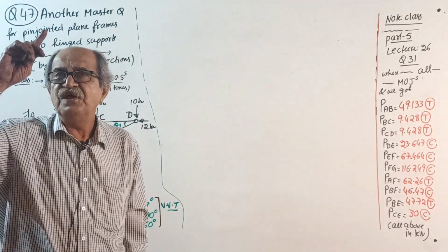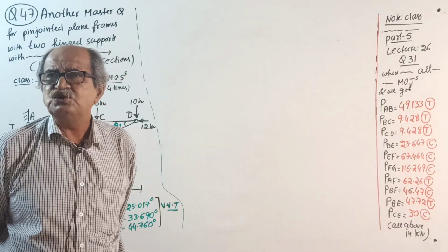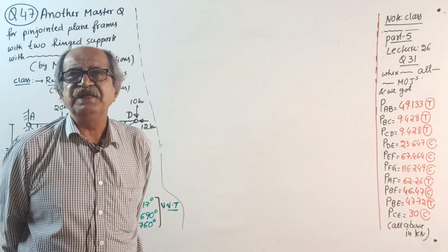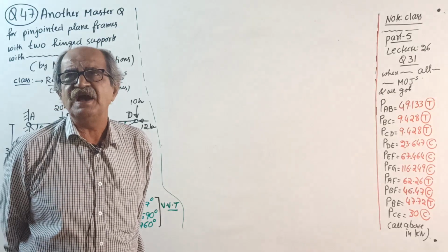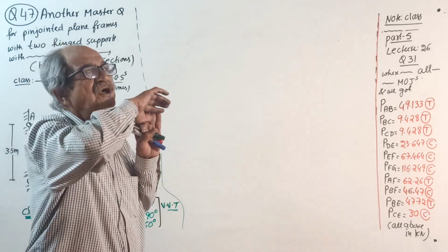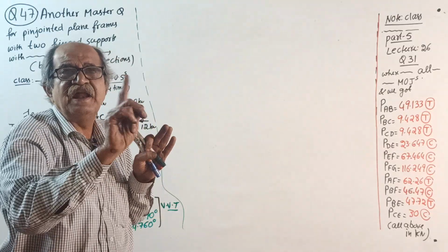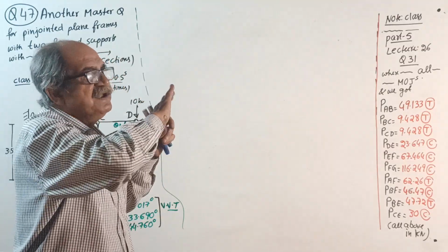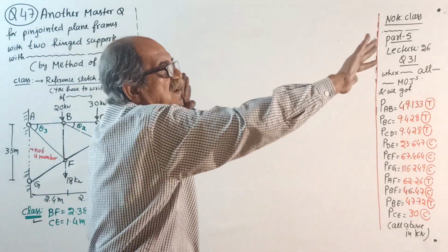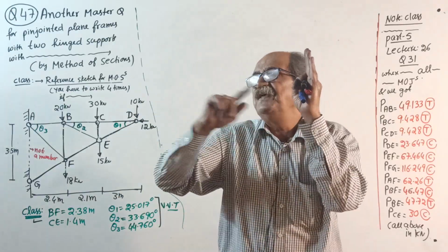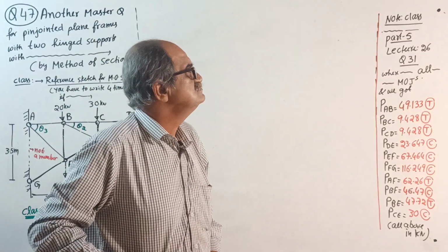See, when you go to SFD, BMD, I will tell. For a cantilever beam, in most cases, for practical design or so many questions, you need not find support reactions. I will tell you to consider the free end side. That's all. Free end side. Don't say right side. If fixed here and free there, look at this side. Or if fixed here and free this side, look at this side. I always say free end side.